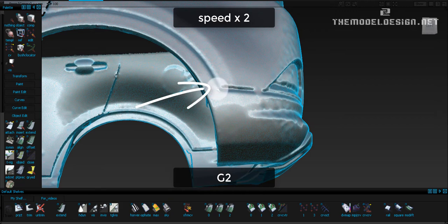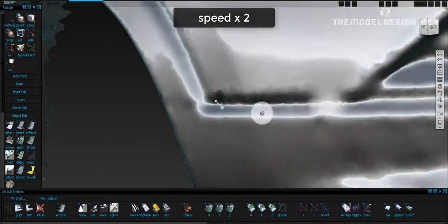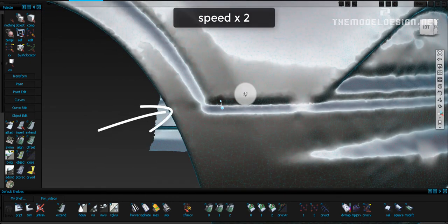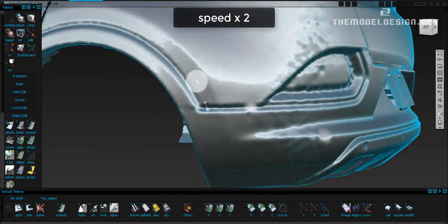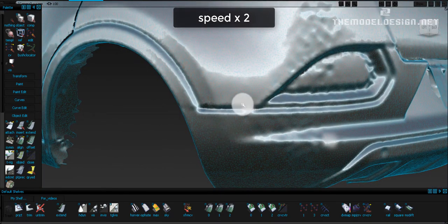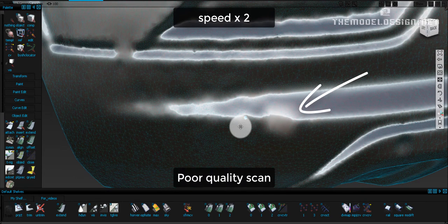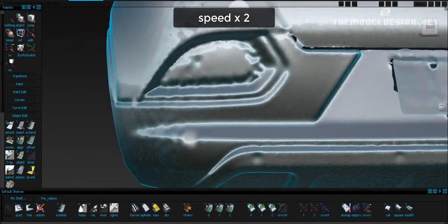And also this area around the wheel arch will be tricky because our bumper will have to somehow connect or blend into the wheel arch. We would need the G2 continuity here. Fortunately, reverse and fog lamps are not particularly difficult. Just make sure you stay close to the scan and you have good consistent theoretical intersections. You can see that there are problems with the scan too. There are some bits and pieces that wouldn't work if we were to take them too seriously.